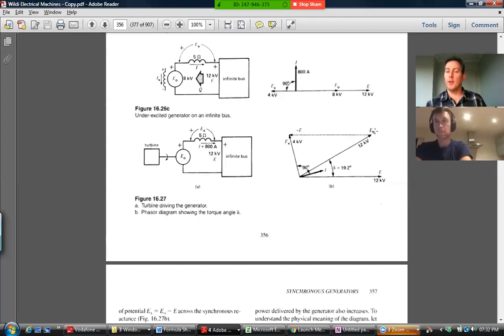induced voltage. Don't forget though, once you've done these calculations, if you do find the product of that I times that E, you'll have an apparent power. That'll be just for this phase. So if you want to look at the power for the load as a whole, you must multiply it by 3. There's no root 3's involved because effectively there's already a root 3 in here. This thing here is already not a line voltage. It's already a phase voltage there.